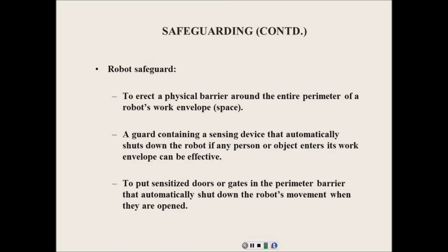Most of the robots, the FANUC and the Motoman, limit the speed in the auto mode, so they don't have a high-speed teach. The KUKA has a high-speed teach. If you use a high-speed teach on the KUKA and you set it to 100%, then that robot is going to move at the program speed. And they do this, of course, to verify path and also to figure out the cycle time.